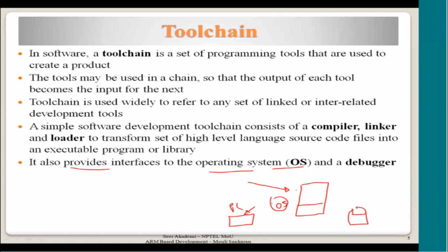In the embedded scenario, normally the OS is also integrated with the application, and then a single executable or image is loaded into the hardware. So the OS is already there along with your own application code. When the processor reset happens and it comes up, the OS comes first, and then gives control to the application that you have made, and then it runs on the hardware. So there must be some way of connecting these two: the OS calling the application or the application calling some routines of the OS. That kind of interface is also provided by the tool.